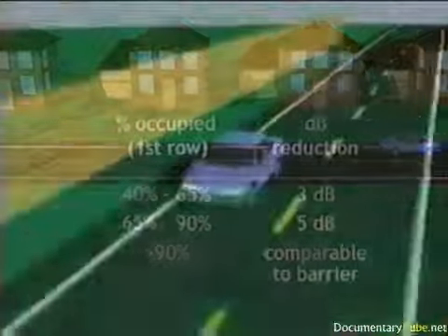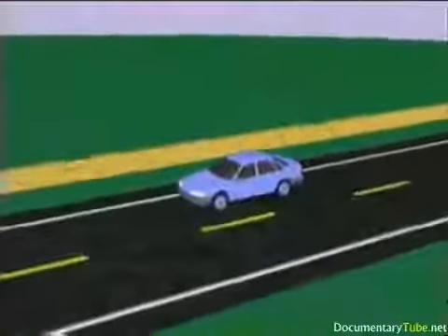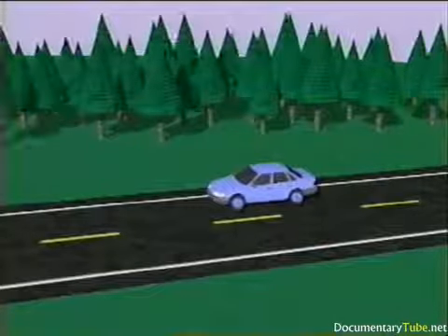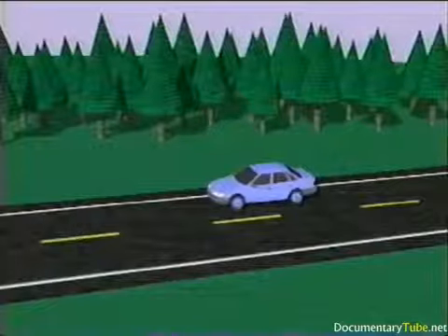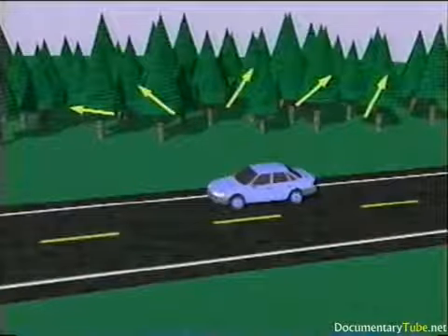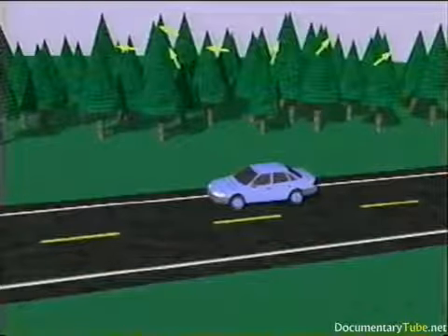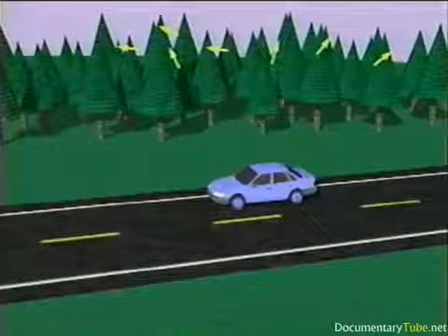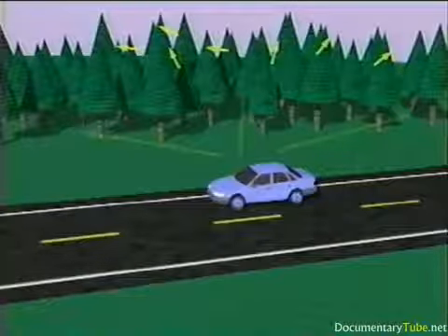In addition to constructed noise barriers and rows of buildings, areas of dense foliage can provide attenuation. Such attenuation is caused by sound scattering into the sky from trunks and limbs, affecting the middle frequencies, and leaves, affecting very high frequencies. Sound absorption by leaves is generally not substantial.